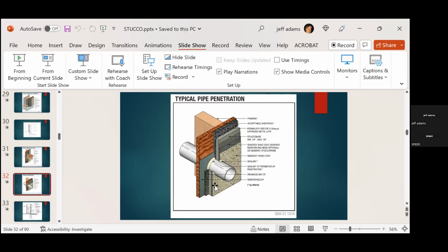Your penetrations. Now, this is not a good penetration. I probably should remove this out of here. They're just trying to caulk and seal this penetration to the WRB. That's not a proper flashing detail. Now, if we used a liquid flash here, okay, but using a sealant to our WRB, horrible idea, never going to hold up and work right. I like those quick flash boots, but you can use flashing tape or whatever, but this does need a better flashing deal. And I'm probably going to remove this slide, but we do need to have a flashing at any of these things, any penetration.